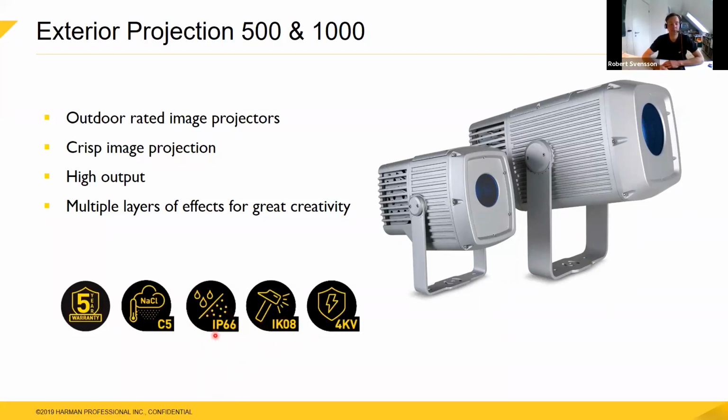And that's also super important, that the product is fully waterproof and dustproof, so you don't get anything inside the product. But it's not really the full story, because if you have a fixture that needs to be outside in an environment for years, then you need a bit more than just an IP rating. So that's why we also have our products designed and verified for a corrosion standard. It's a fairly high corrosion standard, which means that the products can even be used in coastal areas or other places where you have a high salt content in the air, in the rain.